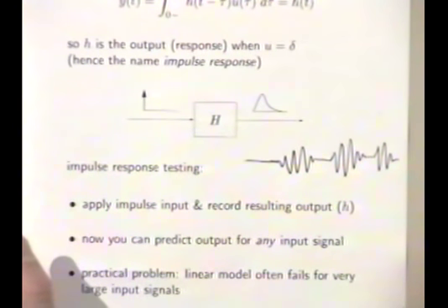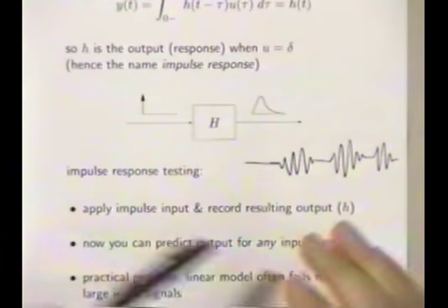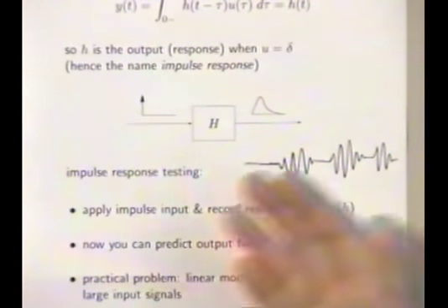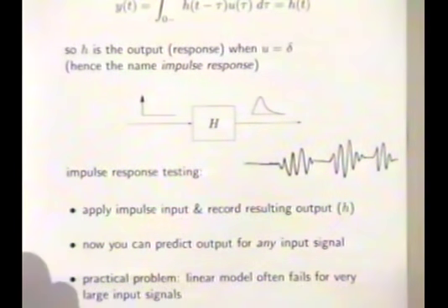In other words, if the impulse response is kind of flat for a while, doesn't do much, and then all of a sudden goes up like that, you know what you have here is that there's going to be a delay. Okay? If the impulse response immediately does something and calms down very quickly, what you have is a fast system, that whatever it does, it has a very short memory and it does it quickly, this kind of stuff. So you'll get that idea.